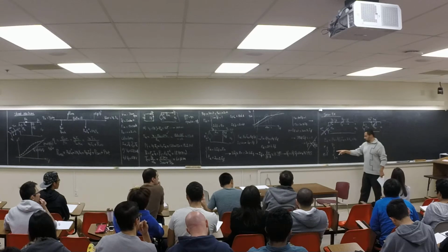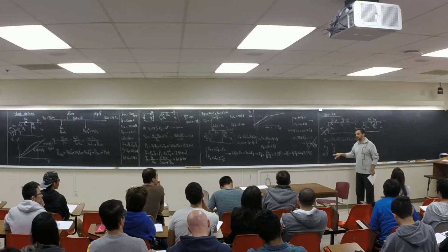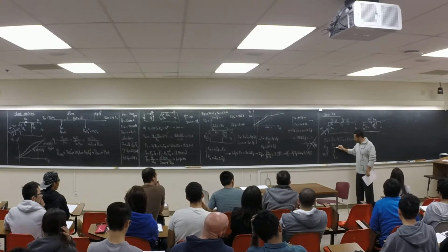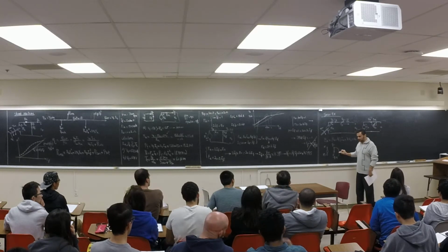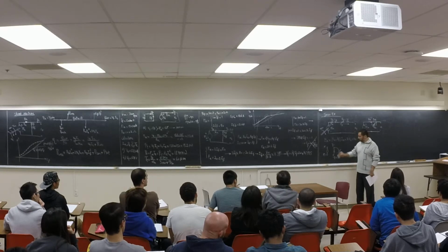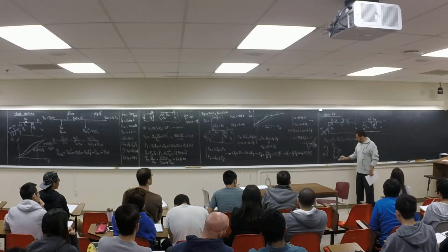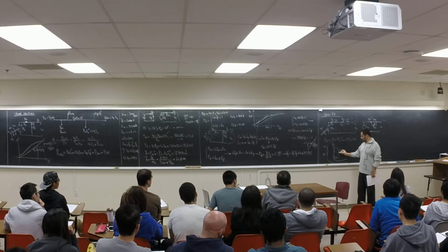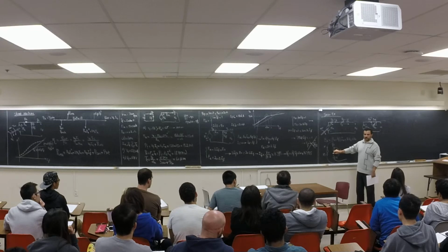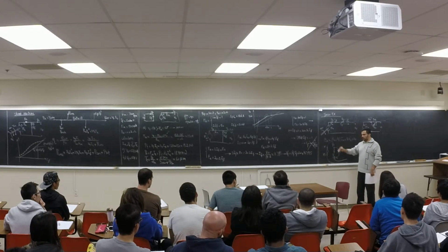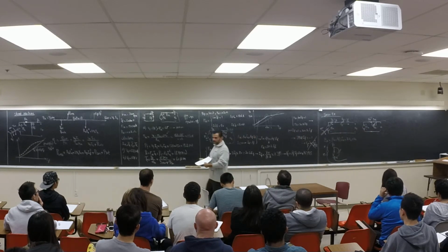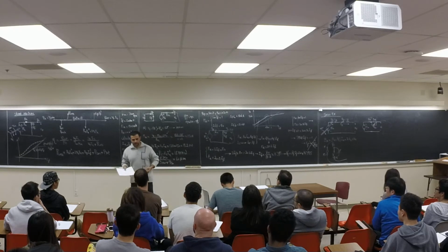Now, if you're going to change the current here, this is fixed. You cannot go inside the machine and change the winding. But what you can do, you can put another stud here, right? You can connect this one with a wire here. Now, see? This is your circuit, right? So you can go change this one. If you change this one, you can change the current in the field winding, right? You're going to see most of this in the lab. The good thing is when you go to the lab this week, you'll see lots of this, so you have to do the connection yourself.